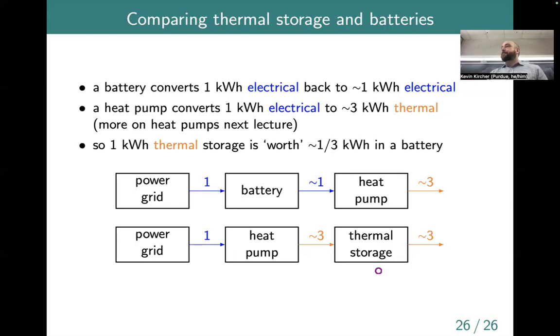Yes. For a thermal battery, is the time constant significantly larger than that of an electrochemical battery? So the question is about the self-dissipation time constant. For what Arash called active thermal energy storage, like a water heater or an ice storage system for commercial air conditioning, I think the time constants are fairly comparable between those systems and batteries.